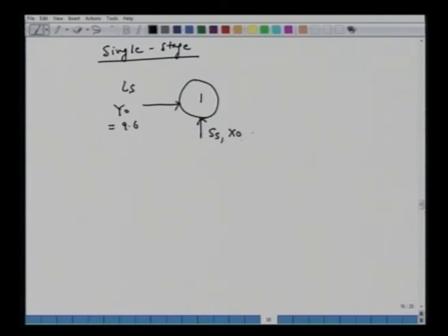All right, x0 is 0. Let's say pure carbon we have, pure charcoal. And after treatment we have Ss, and this unit is x1, and the solvent leaving, this flow rate is Ls, but the concentration is now y1 equal to 0.96 kg or units of color per amount of solvent.